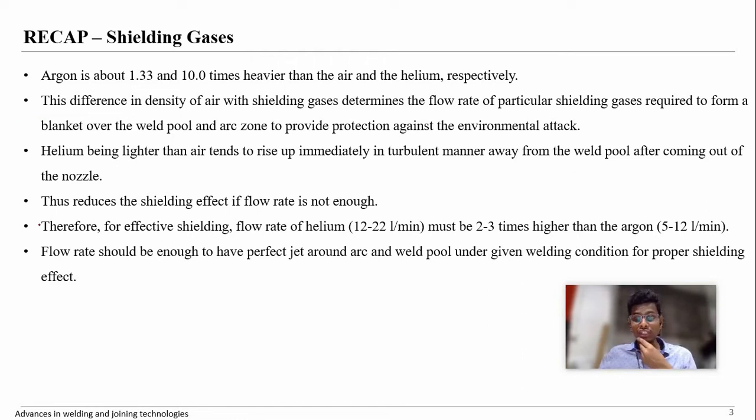Basically, we discuss density because it determines the flow rate which needs to be used so that an effective blanket of shielding gas can be achieved during the welding process, so that we achieve good mechanical properties as well as a sound joint.